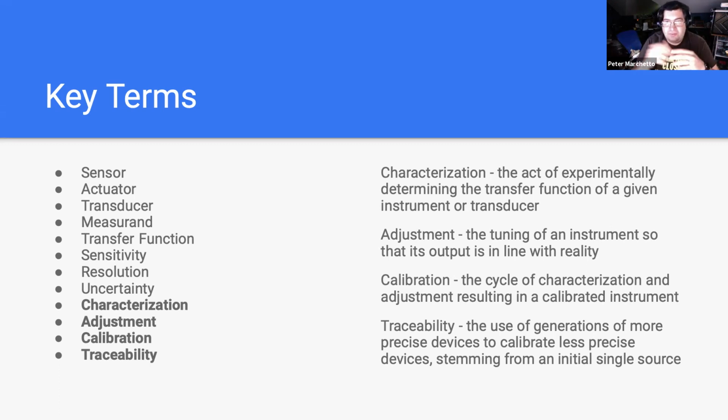I don't have to file it. I don't have to readjust the micrometer if that's the thing that I'm calibrating. The adjustment part is a zero adjustment, but there's still the option to adjust, which means that even though I've only characterized the relationship between the gauge pin and the micrometer, there's still a calibration that's occurred. It's just that the adjustment is 0.